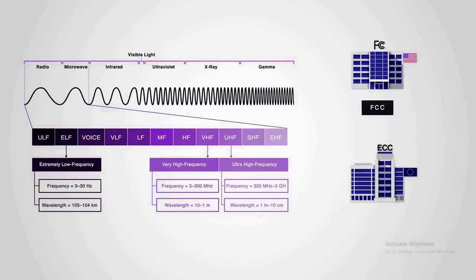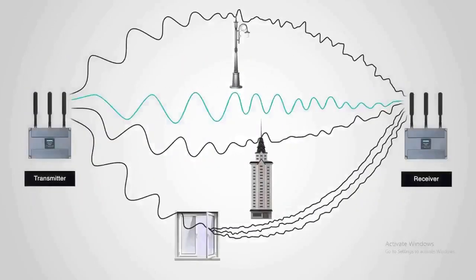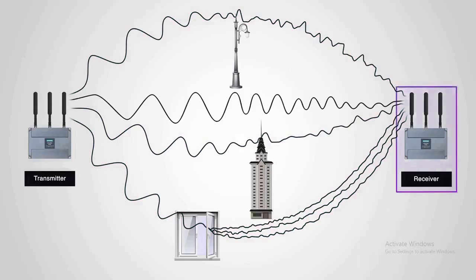An electromagnetic signal does not go straight out to a receiver after being transmitted, but it radiates the signal in multiple directions. Radio waves can reflect off buildings, they can bend on sharp edges, or even scatter on small objects and still be able to reach the receiver. During this, the waves radiated along multiple paths endure different types of attenuation and delay. The receiving antenna captures all the waves as a combined signal, and when the wave travels more than one route, it is called a multipath channel.